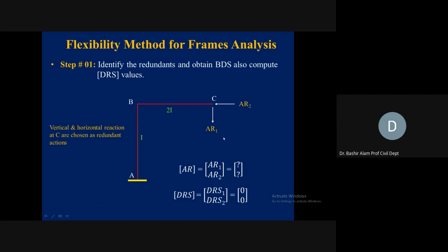Why? These are just opposite to whatever we did in problem 1 and 2. This is just to show you the freedom, the liberty, that initially you can assume any direction. Don't waste time thinking whether this is going to be upward or downward, leftward or rightward. Straight away you take one direction and that becomes your positive reference. Finally, you will get a result. If it is positive, it means your assumption was correct. And if it is negative, you just reverse the direction because the magnitude will still be okay.